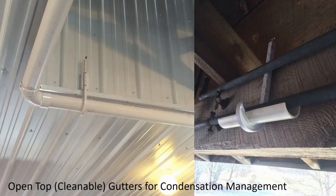On the right-hand side, again, just an example. It's a short section of PVC just to demonstrate the idea. There's a pipe hanger, that white J-shaped thing, and what it's holding onto is half of a 3-inch diameter PVC pipe that's just been cut down the center. A longer section of that would be hung underneath that cold water line. This is in a wash pack shed in southern Vermont, where the summers get pretty humid, and they are running a lot of cold water. So you get condensate on that pipe, and it drips, and there are handling areas, sorting tables, and packing tables underneath. We want to make sure that condensate does not find its way to the produce going to the consumer.